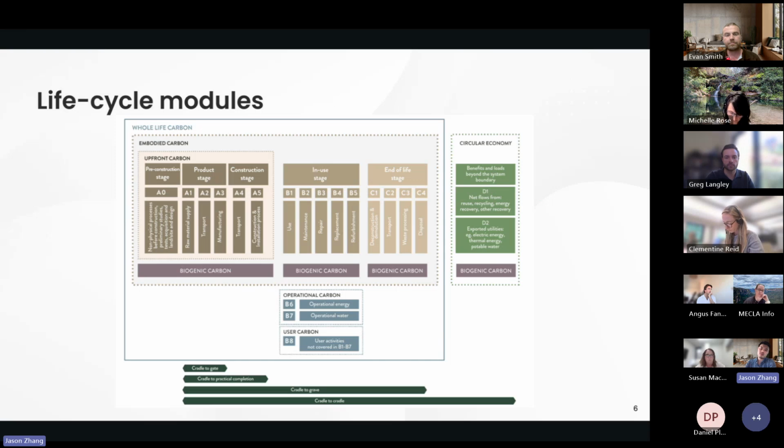Yeah, that's right. Normally A4, A5, and those are all scenario based and based on assumptions. So when reading an EPD, it's really important to make sure you capture those assumptions or scenarios, and then you understand this is not a static figure. When you do calculations yourself, you need to actually adjust this figure based on your project location.